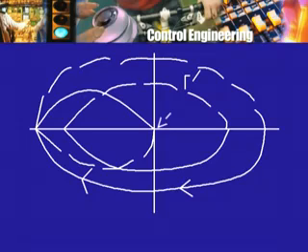and this is corresponding to that semicircle business, a point which is very close to the origin, or the part of that curve is very close to the origin. So, I can essentially show it as going through the origin. So, this is going to be the polar plot, or the entire Nyquist image of the Nyquist contour. This is going to be gamma prime. Now, remember, I have to put arrows, and I did not do it earlier. So, let me now put the arrow on the dash part also.